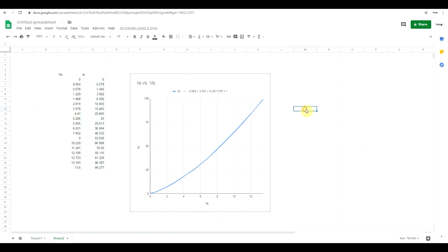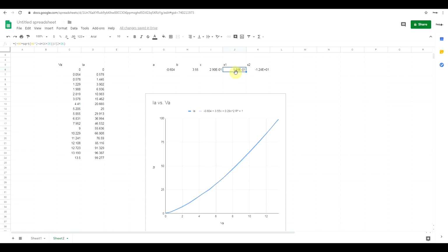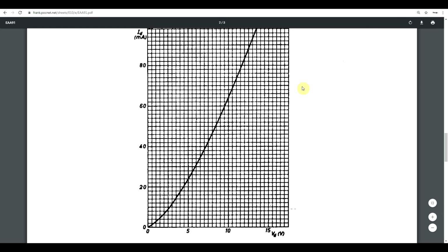And now, well, it's a bit better. So my first term is now minus 0.6, so it's a slightly better fit. But I'll still try to get out the solutions to my equation, so simply fill in the free terms. And now we know that if we start off our graph at 0.168 volts, then we will have a very good fit from this equation to our implementation. So let's see how well this works in LTspice. Let's see how well we can implement our datasheet curve into the simulator.